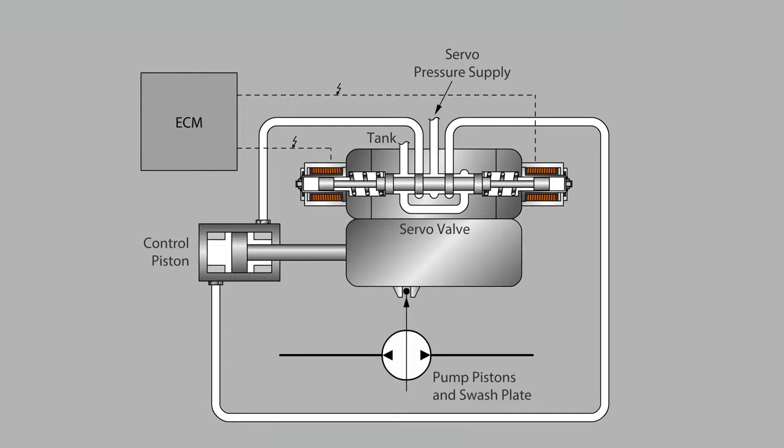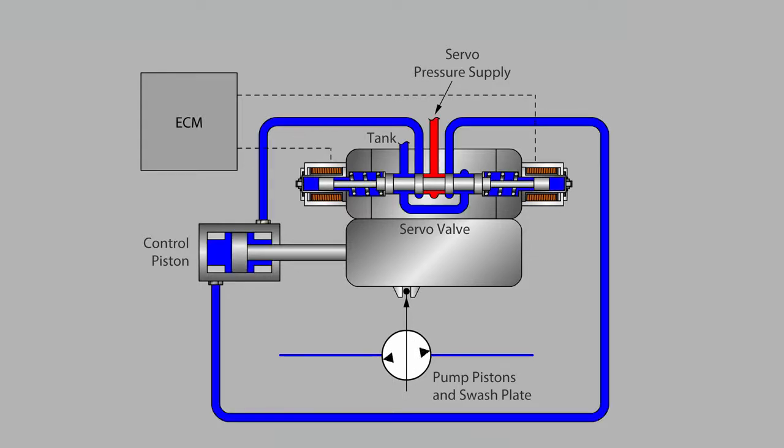In this video, we will look at a simple model for controlling the direction of flow and the flow rate from a variable displacement piston pump. In this case, it is a pump that is typically used in a closed-loop hydraulic system. A closed-loop hydraulic system is sometimes referred to as a hydrostatic system and is popular for operating hydraulic motors that propel a mobile machine such as a skid steer loader both forwards and backwards.